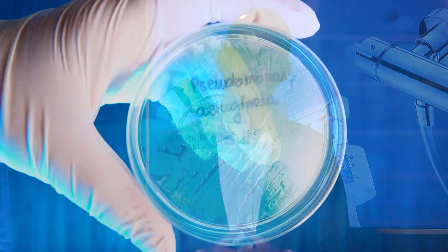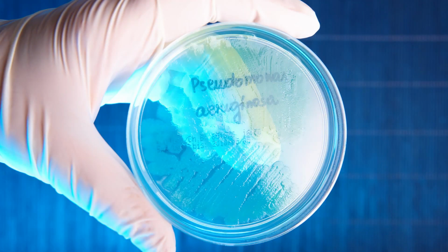Also, the Health Technical Memorandum 04-01 Part B, which was published in 2016, requires that the control protocols are monitored and maintained as identified in the risk assessment and water safety plan for both hot and cold water systems. Also, this guidance recommends installing taps that can be removed easily to be cleaned and disinfected. So at Delabie, we don't just offer solutions that comply with the guidance and respond to the challenges of Legionella and Pseudomonas. We go even further.